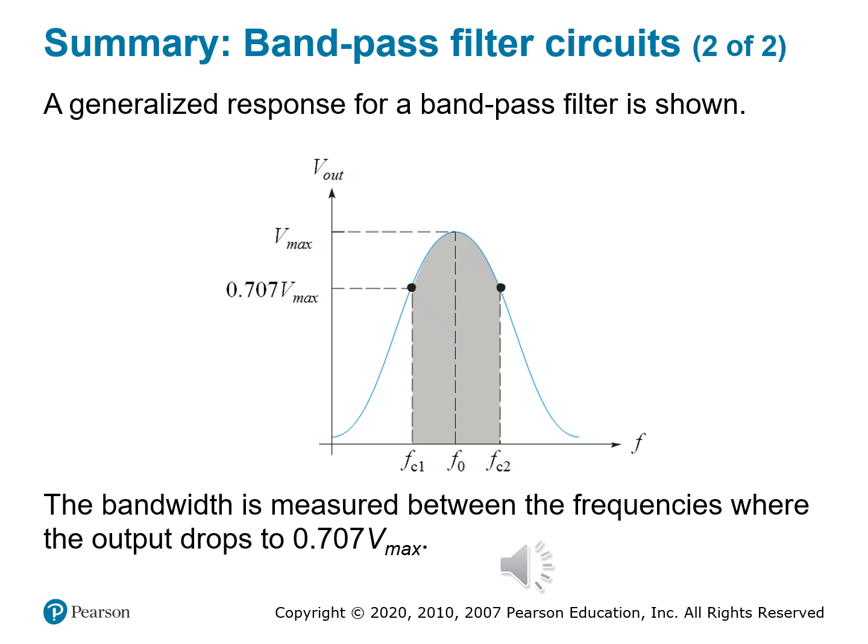If you look at the left and right of that peak, you have two key points, F sub 1 and F sub 2. The output drops on both sides to 70.7% of the maximum. And why that number? Remember, this corresponds to the negative 3 dB point, which is a standard threshold in filter design. The range between F1 and F2 is your bandwidth, the frequency window where your signal is the strongest.